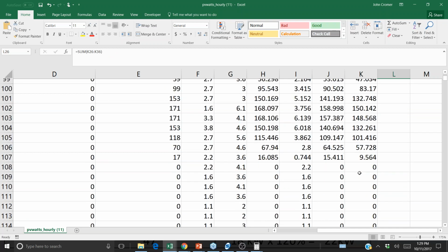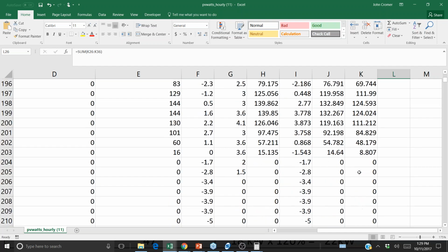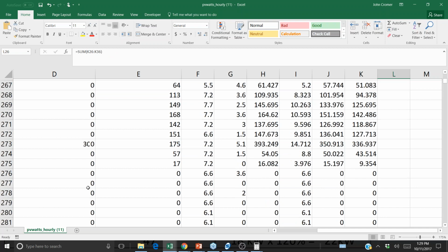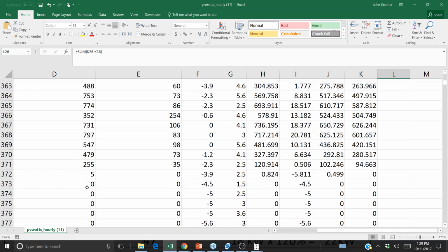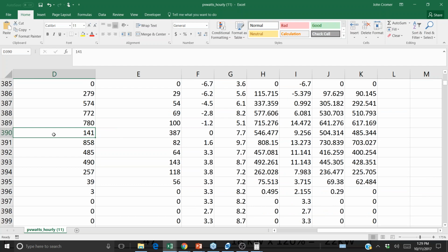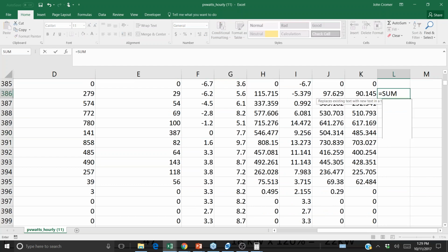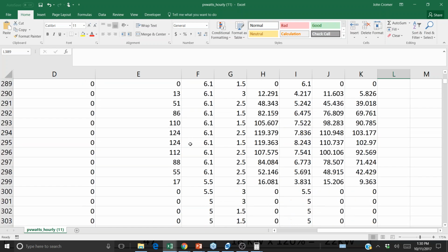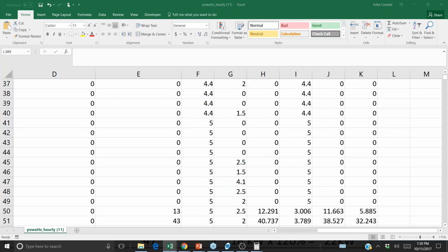Let's go ahead and scroll down to the sunnier day, where we have a lot of direct irradiance. So here's a fairly sunny day, although we do get a cloud at high noon. And on this mostly sunny day, that 1 kilowatt array is producing 3,815 watt hours. One takeaway is that you will produce some power out of your array on an overcast day. You'll produce about 20%, maybe a little bit more than 20%, out of the array on a cloudy day versus a sunny day. And so what we do in our solar design is we can take